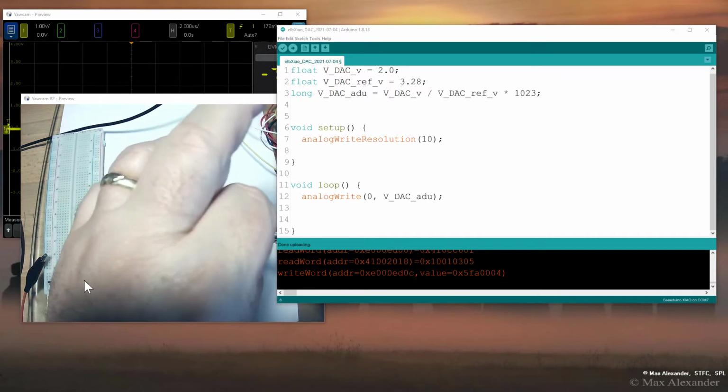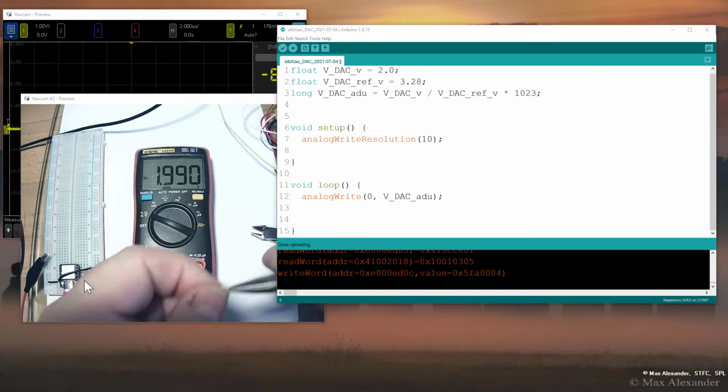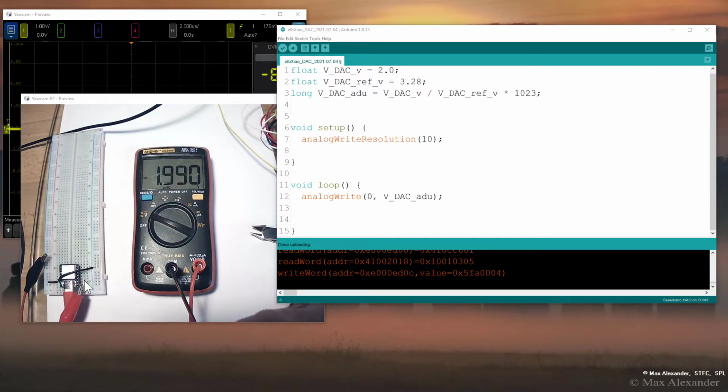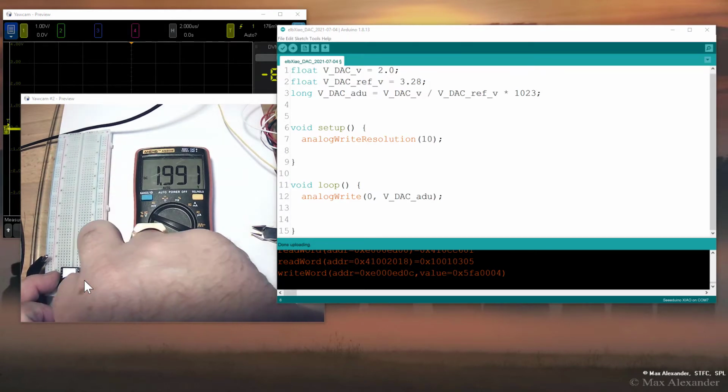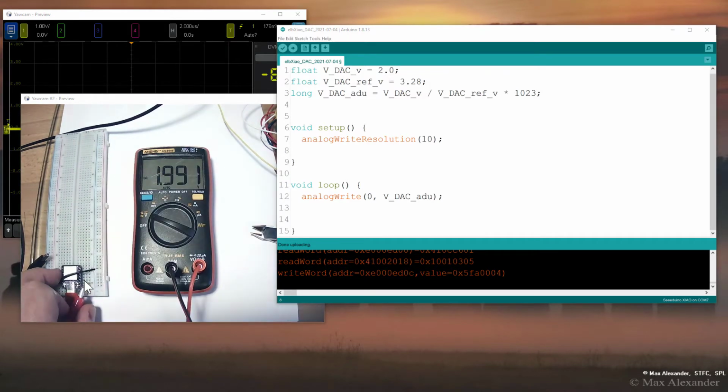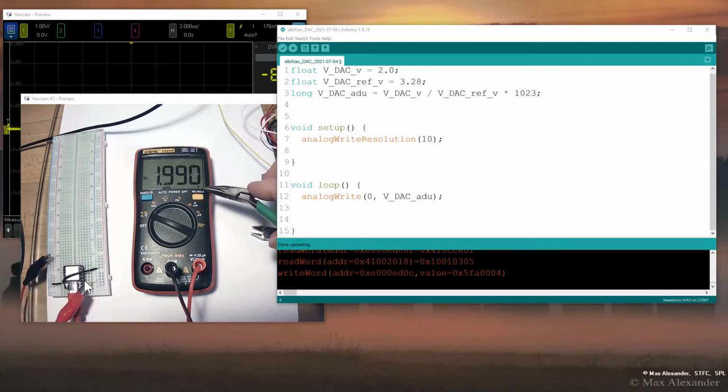I'm going to use it to short out the adjacent pins in the JA module that'll connect the DAC and the ADC. And so here we go. It's these two pins here, and we're done. We're still monitoring the output voltage from that DAC, and now it's the input voltage to the ADC. We've got something to measure, and now let's set up the code.